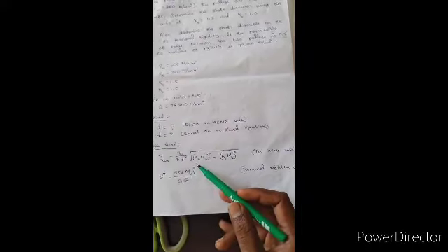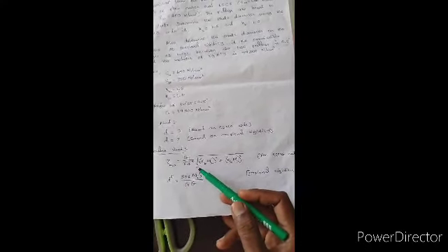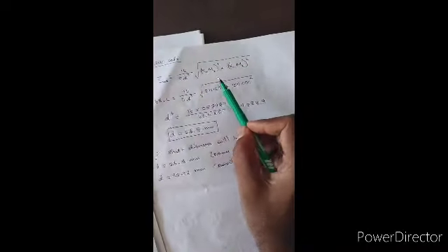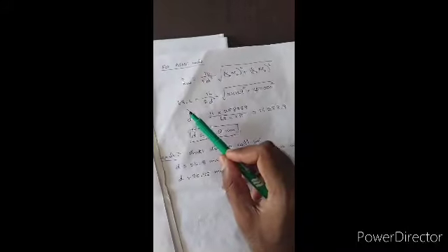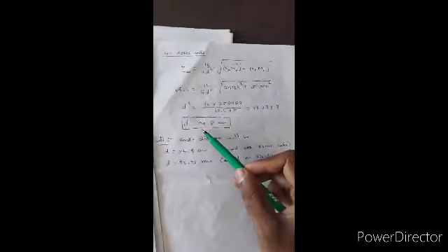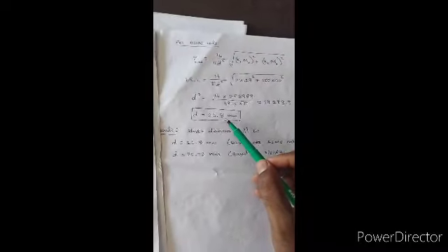Already I have the MT value. We know the formula: for the ASME code method, tau max equals 16 by pi d cube times the root of (kb mb) square plus (kt mt) square. Now substitute the values. Kb value is 1.5, kt value is 1. Kb into mb will be equal to 21129, kt into mt equal to 150000. Tau max value is 68.4. Substitute all the values, now we got d cube as 19283. Take the cubic root, you will get the answer as 26.8 mm.